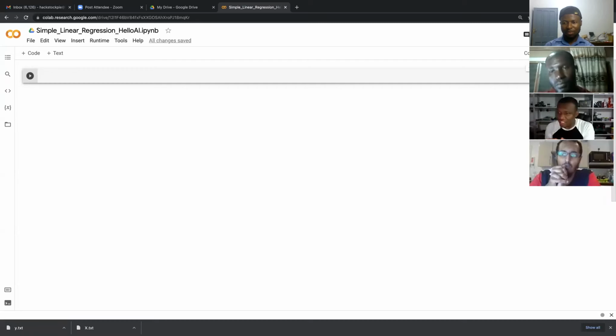So if I'm going to use 4 motors on my robot, and I want to avoid the use of encoders, buying this motor costs $50 for one. Some of them cost $1,000 for one motor. If you can't afford that, you have to go for this Alaba Market motor. Now, for all 4 of the motors, you need to use regression to estimate the relationship between the voltage applied and the RPMs that you'll be achieving.